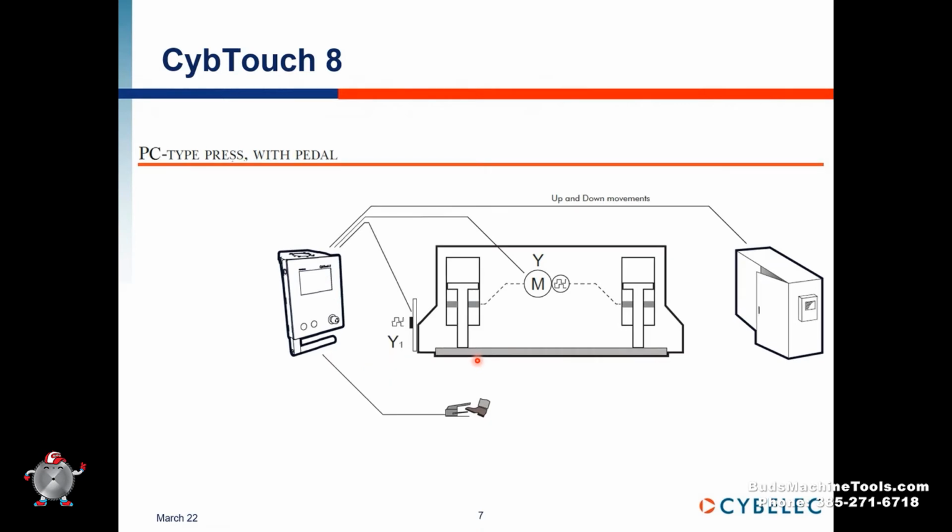And then PC is the same as the P, except we remove the switches here and we add a linear encoder. With this, we are more precise to know where the beam is. Of course, the bottom dead center, the beam will anyway go onto the mechanical stop. So we reach the precision with first positioning the electrical axis.